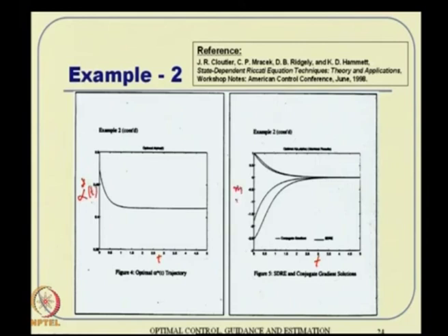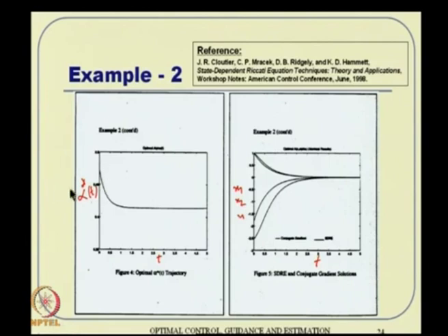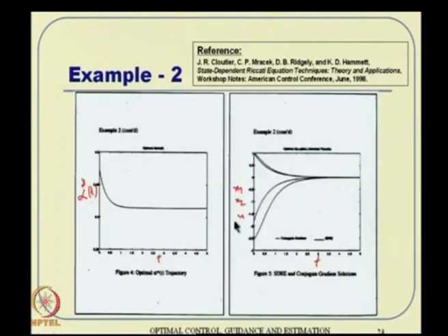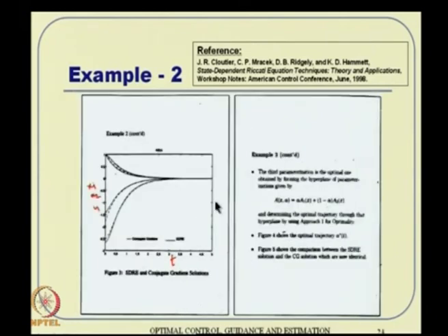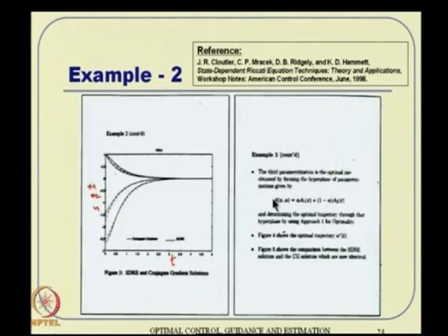And here is regular x1, x2 and u. If the procedure allows that, in other words, if this alpha star tuning is not very computationally expensive, if you can do it in closed form, then why not do that online also. You can also see that very quickly alpha star converges to some constant value. So you keep on computing alpha star, then compute an A which is a function of that alpha, and apply SDRE using this newly constructed A.